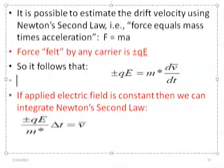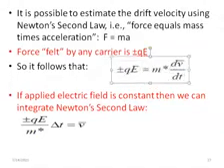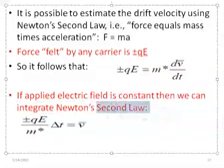So when this applied field, that is the voltage, is constant, then we can integrate this relation to come up with the formula for the velocity. Here, this our dv, when integrated, will give us v, which is equal to QE over m, that's the mass, times dt. dt is now the time period during which that electric field is applied.